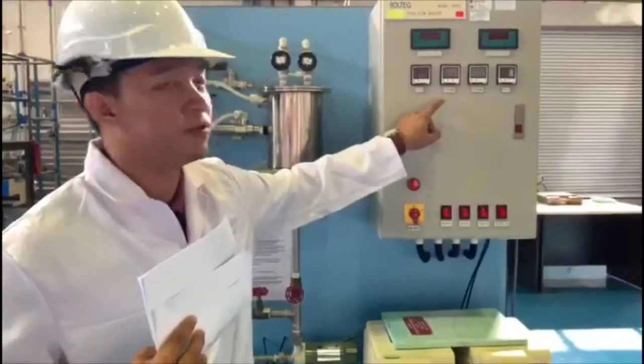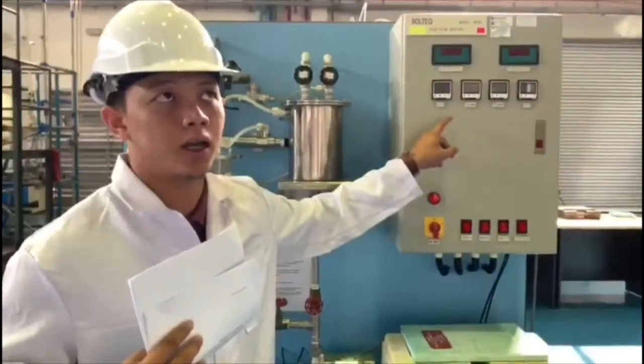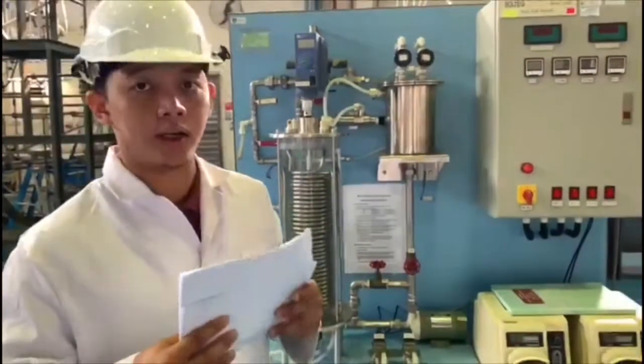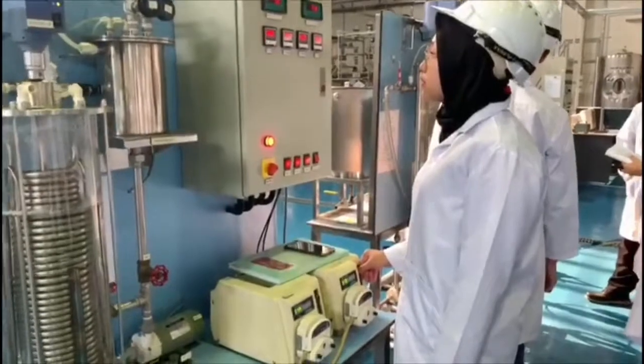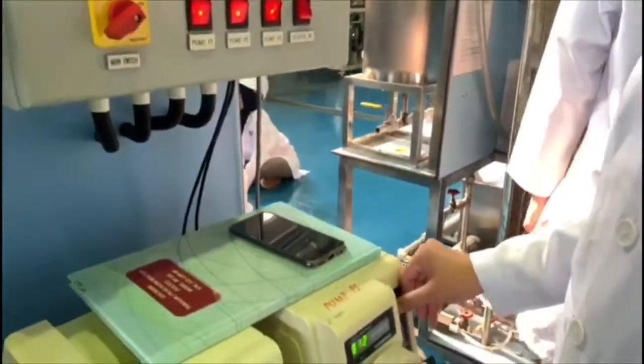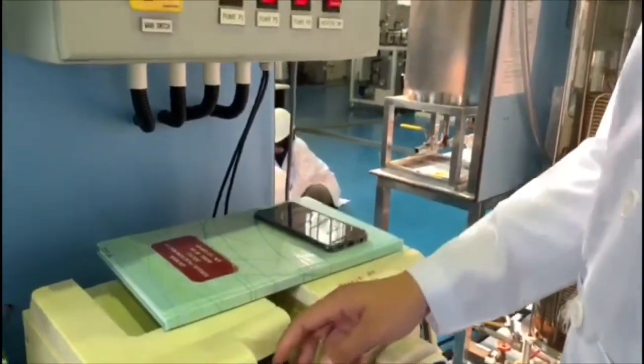Ninth, open valves V13 and V18. Switch on pump P3 to circulate the water through preheater B5. Switch on stirrer motor M1 and set the speed to about 200 RPM to ensure homogeneous water jacket temperature.